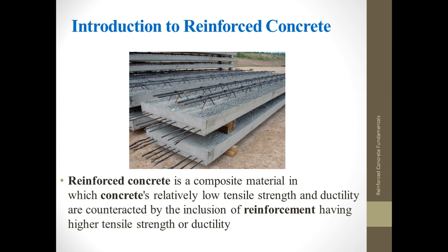In this picture, we can see the steel bars, as I indicate right here, going out of the concrete. We call those steel bars reinforcement, and the term reinforced concrete actually comes from there. We are adding the reinforcement into concrete actually to increase its tensile strength. As we will discuss in the upcoming modules, concrete's compressive strength is quite high, and the problem with it is its low tensile strength. By placing those steel bars, we are increasing the tensile strength of the material.